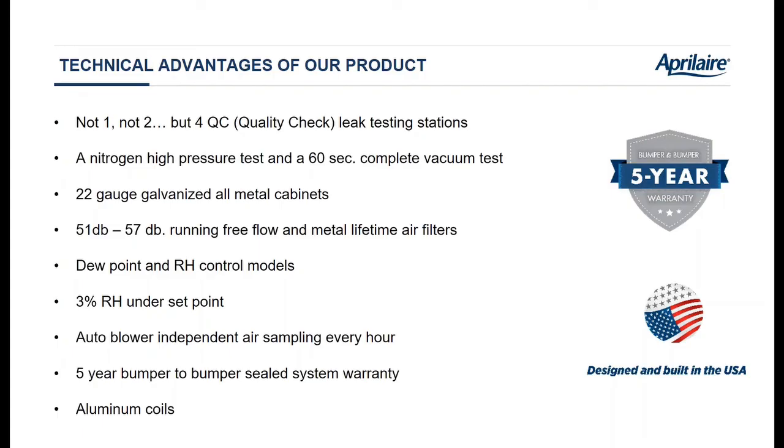What's going to cause a portable dehumidifier to fail? You go to the big box store, you buy a portable dehumidifier, 3 to 5 years later, it's not really dehumidifying anymore. That's because, let's say you set that unit to 50% relative humidity. It's going to come on at 51, it's going to shut off at 50. Remember, it's not moving much air, so it's not going to take very long to dry that bubble of air out. So the compressor turns on, turns off, turns on, turns off. We all know compressors like to run, compressors do not like to start. That is a significant shortening of life on that compressor.